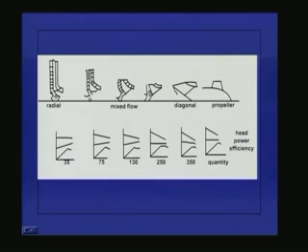Whereas in this figure here, when the specific speed is 350, the power consumption reduces as the discharge goes up. That means if I select a motor for very high discharges, and then I operate the pump at very low discharges by throttling the valve, or when there is a shut off condition, there is overload on the motor.